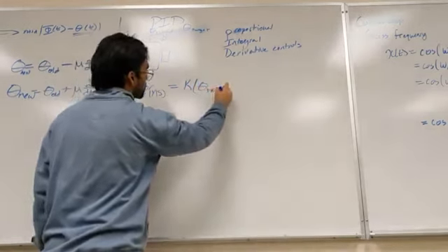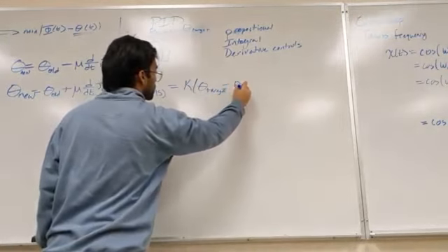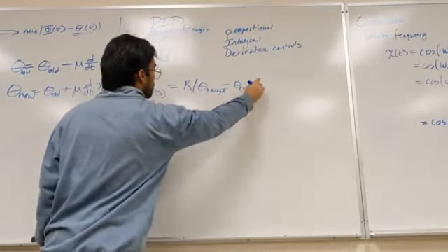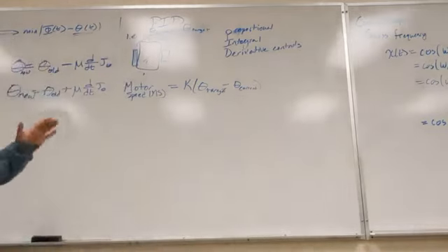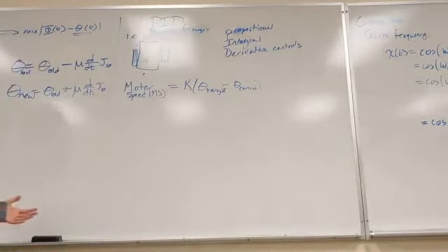And this works because when our target angle equals our current angle, we're not moving anymore. But it turns out theoretically, you won't actually ever reach your target angle with just a proportional controller. The math behind that, I don't think is necessary to go into.